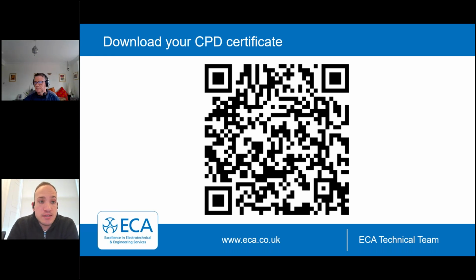The question says, in a WC larger than 8 square meters, does BS 5266 recommend emergency lighting in individual cubicles if emergency lighting is provided in the open area outside of the cubicles? No, well, it depends on the layouts where you're going to be siting the emergency lighting in that area. There will be a consideration for people within the cubicles, that they can see what they're doing and they can get out, of course. So not necessarily.